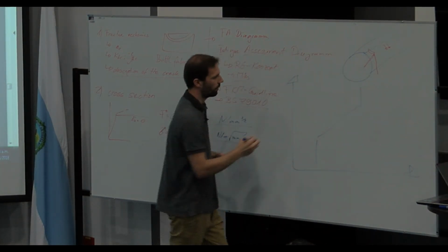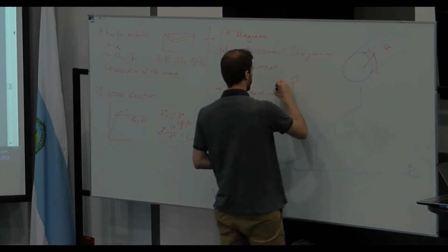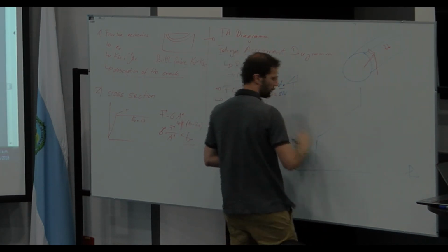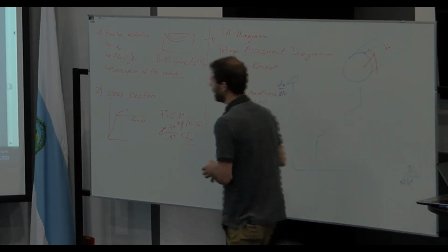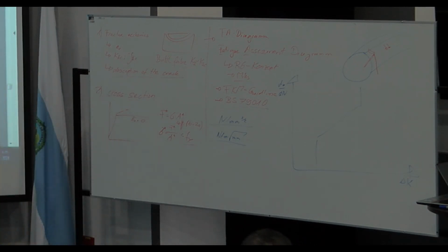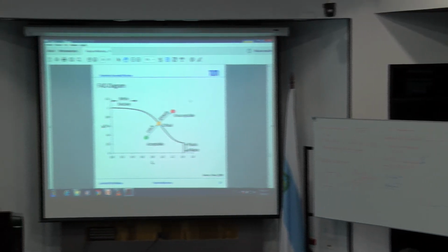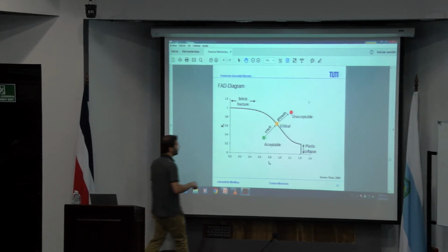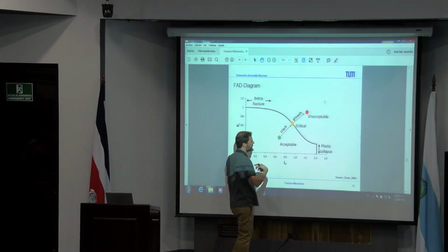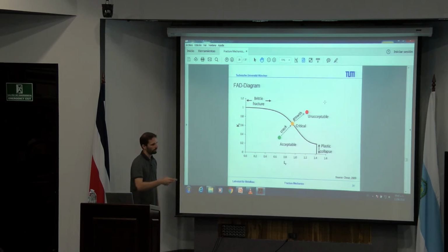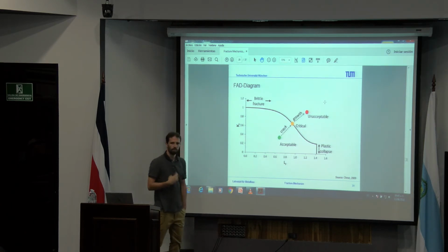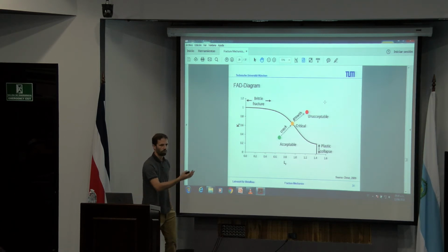You have here the dA/dN over delta K. And so you have your basic information about your material because you were able to conduct some crack propagation tests. And so you know, okay, for this point here, there is still some time left where your crack can grow, and this crack growth is in this case described by the crack propagation.